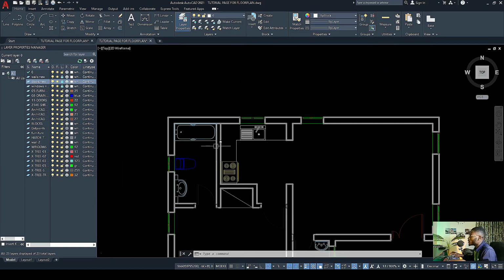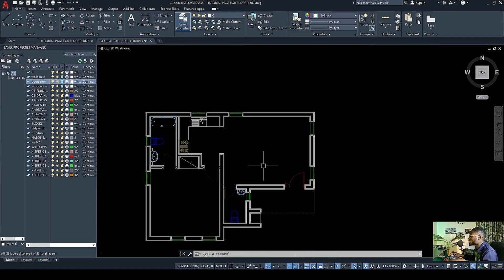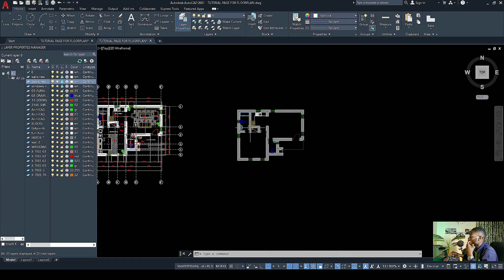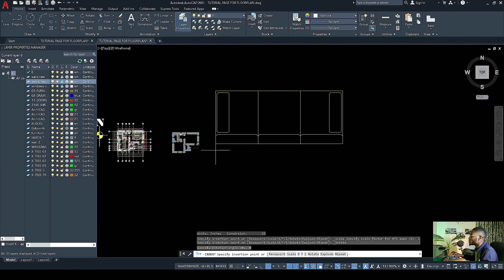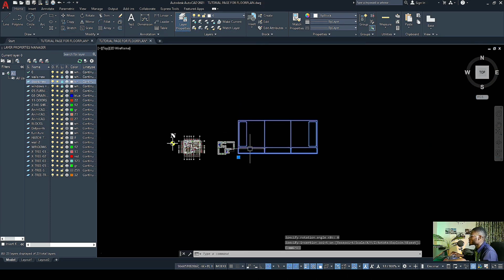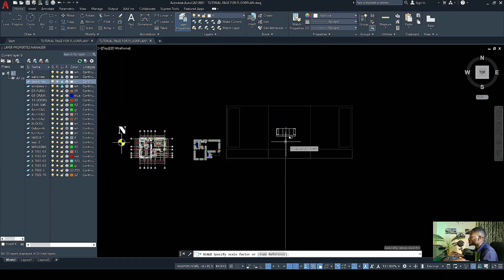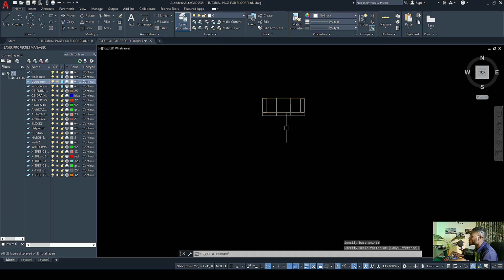So all right, the next thing to do is to introduce our sitting arrangements, our chair furnitures in the living room. So what we'll do quickly, we can also come to our insert. I have my chairs here, and copy and bring them in. You see it's in a bigger scale. So to rescale this, I can just click on it, then scale, then reduce it. It was in a very bigger scale.